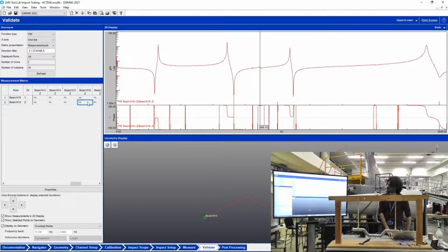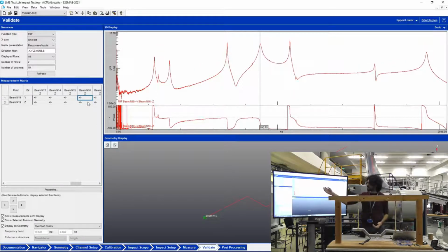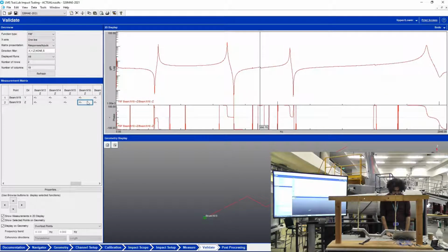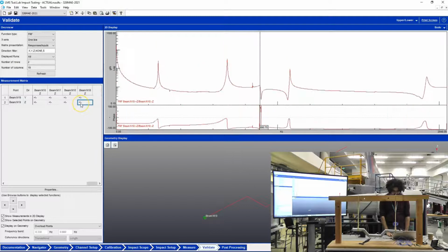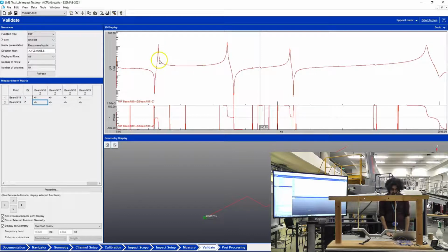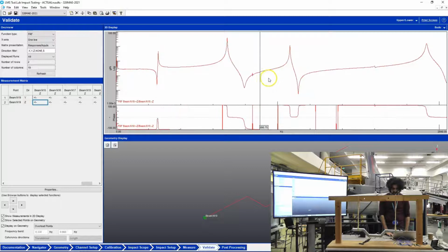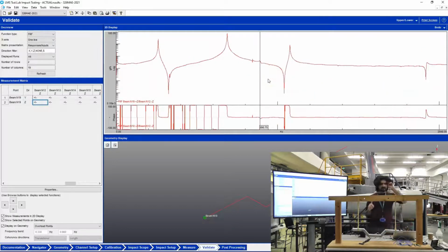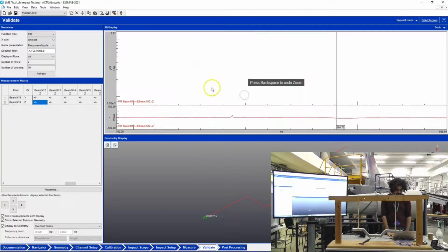Of course, in the z direction it looks tiny, because we're looking just at this vertical one, and in the y direction it looks larger. So these are all very nice, and I'd say we have 4 main peaks: 1, 2, 3, 4 in the z direction. So we have four modes of vibration in the vertical around the frontal axis.